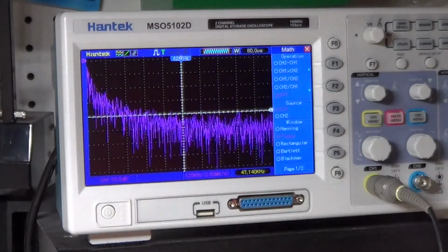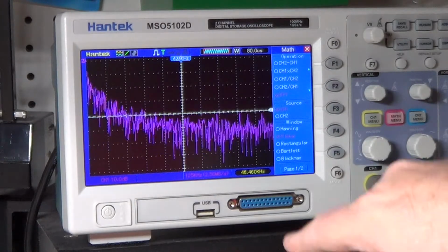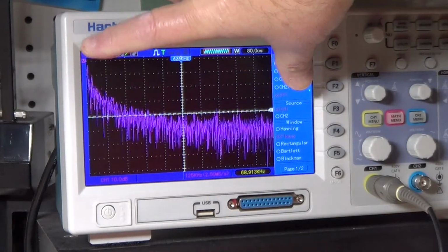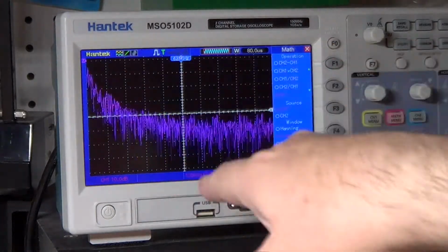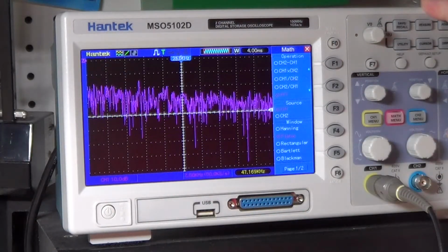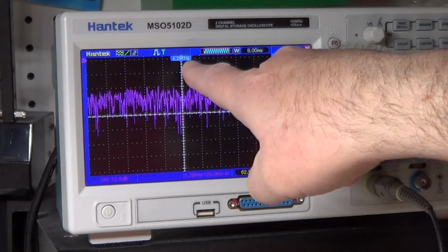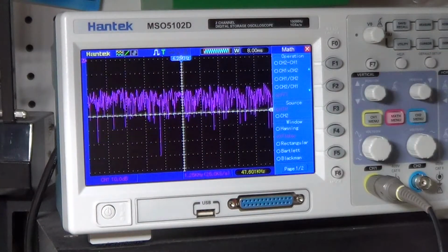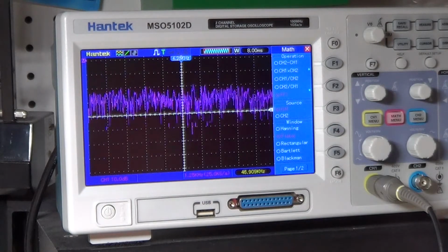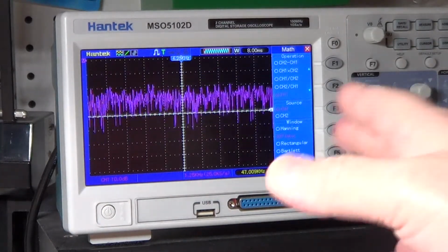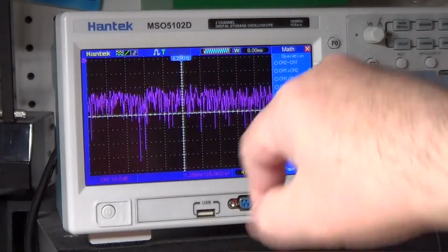This is the spectrum of the filter. Right now it is set with a 1.25 MHz range. Now let's talk about this a little bit. Let me reduce the frequency here. So we are now centered at 6.25 kHz. We know that this filter has a cutoff frequency of about 16 kHz. Here we are before the 16 kHz, so before the cutoff frequency, it is basically almost flat.